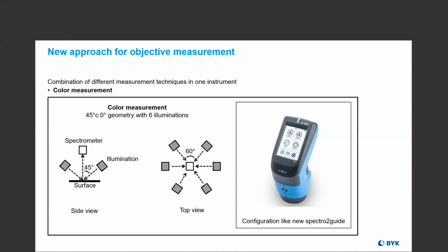It just means that the spectrophotometer can be oriented any way on the surface. You can take a measurement, turn it 90 degrees, and take another measurement. You should get consistent measurements no matter which way you turn it. So by the way, circumferential illumination, that's what the C stands for in 45C0. That's kind of a new notation, but 45 is for the angle of the light source, C is for circumferential, 0 is the angle of the detector.